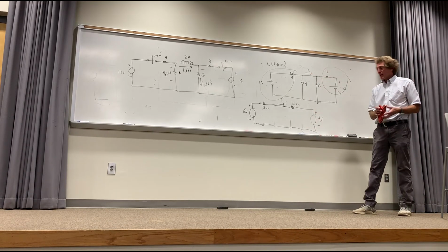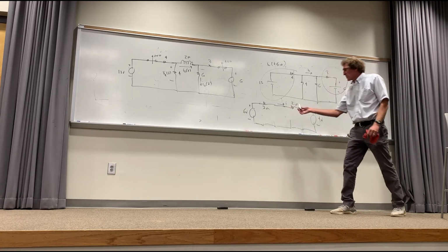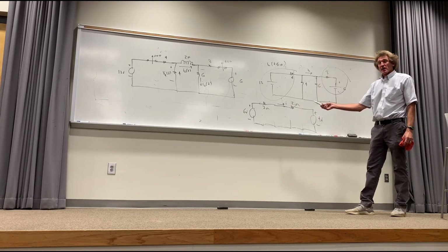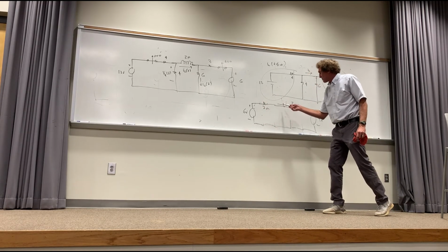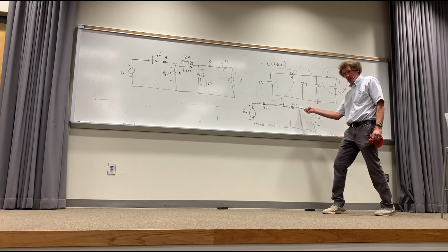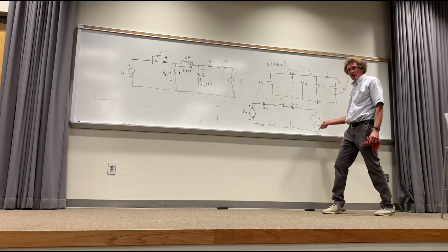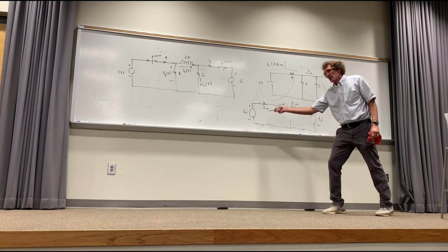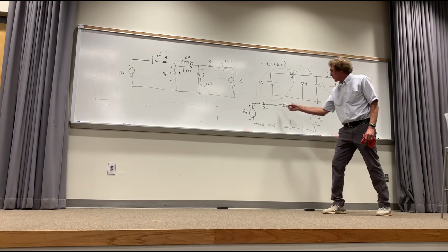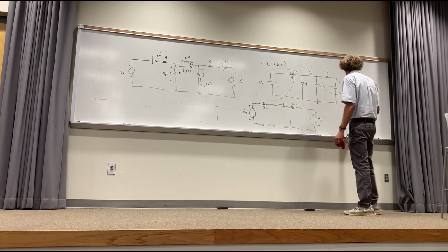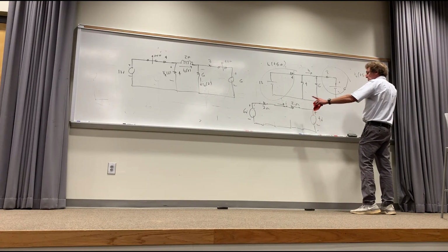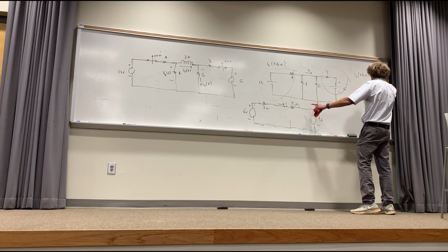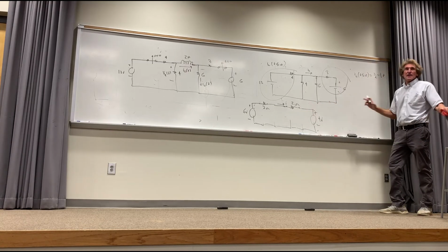With me? Now, pay attention to this. When I take a look and I want the net current flowing that way, just follow me. If I start here, voltage increase is 6, right? Minus 2 times I, minus 2 times I, or minus 4 times I, and then minus 4, right? So I have a net of 2 volts pushing current around, and it's going through 4 ohms. Do y'all agree with me? And that means that current, for t less than or equal to 0, is going to be equal to 2 over 4, or 1/2 of an amp. Do y'all see that? You can do the math on this one later.